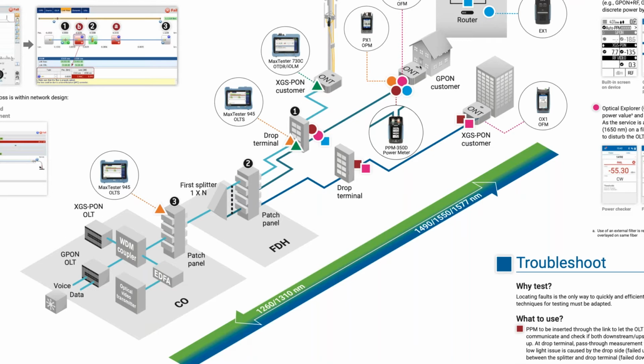And then our first splitter is a 1x8 splitter, and it has about 10 dB of loss, which is what was to be expected, no reflection. And then my second splitter, I've got roughly 10 dB of loss as well. And then out beyond that, we start to lose some of the resolution just because the losses are so high.